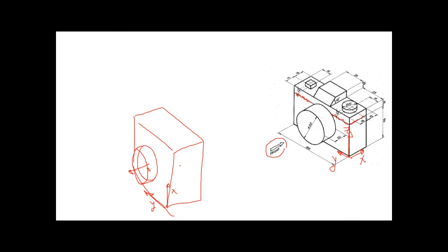Now you move to the top. What can we do with the top? Again, you locate that circle first, and then you draw your circle, and then again you make your press pull to end up by drawing that cylindrical part. Clear? And then you go and locate your little box, and then again you make press pull to end up by drawing that cube.